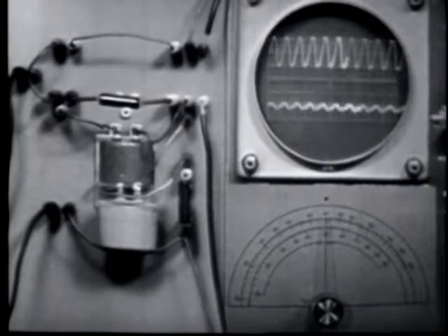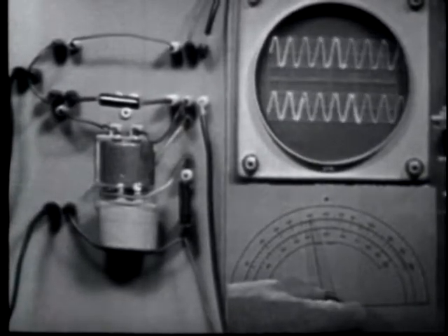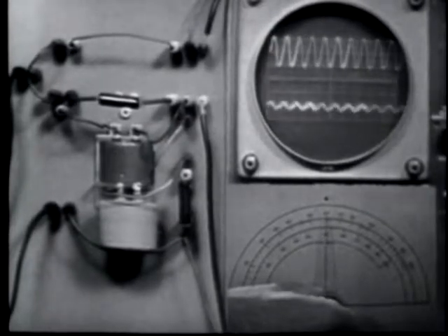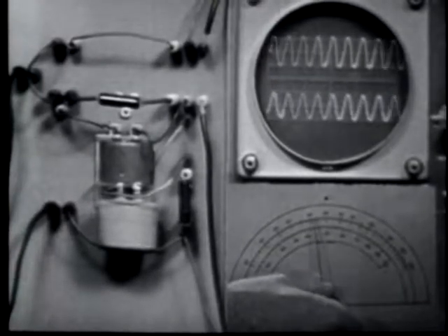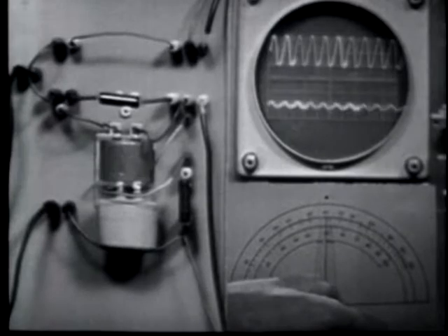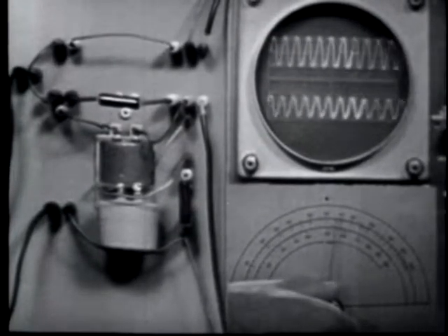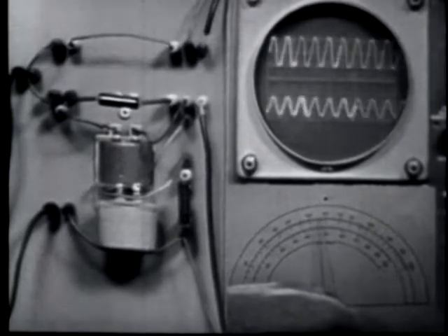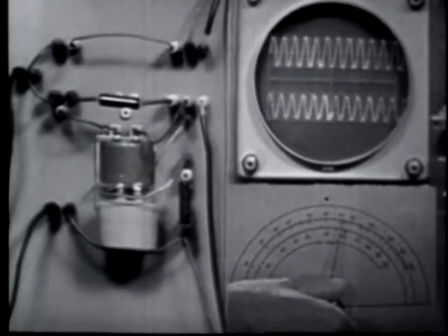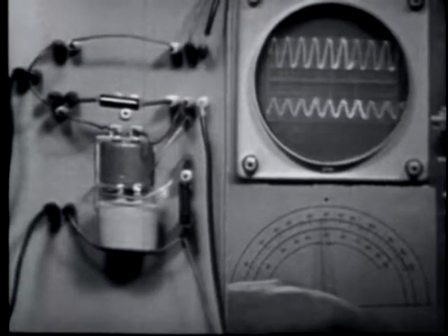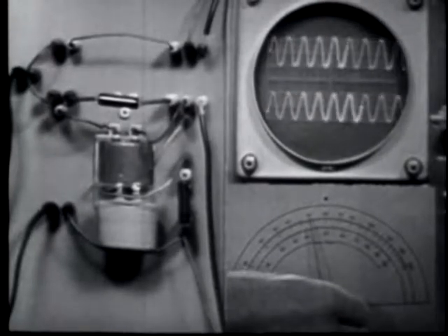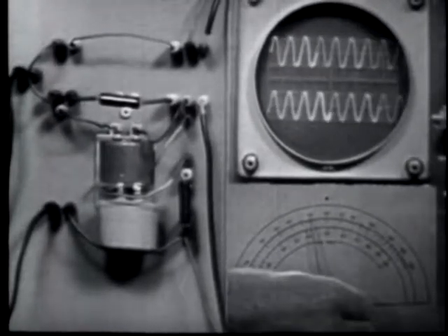Now the parallel tank is offering maximum impedance to frequencies close to resonance and rejecting them, and the series tank is offering minimum impedance to frequencies at resonance and is not developing an output voltage. The filter is now rejecting frequencies at and around resonance. At frequencies off resonance, the parallel tank impedance is minimum and passes these frequencies through. The series tank impedance is maximum and develops the output voltage. The circuit is passing frequencies off resonance. And note the extremely sharp response, since we're now using two tank circuits.